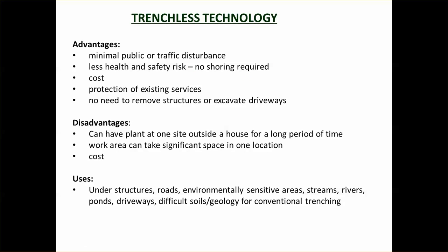So the advantages of trenchless technology is that there's very little above ground disturbance. So you're not having people going down into the holes, there's no shoring required. It can be less expensive in terms of not having to reinstate so much area as you do with trenching, but directional drilling can be more expensive because you're using more expensive materials, and the plant is specialized plant, which makes it more expensive as well. So there's a balance there, and it comes down to what the situation is, whether trenchless technology or trenched technology is the best way to go.